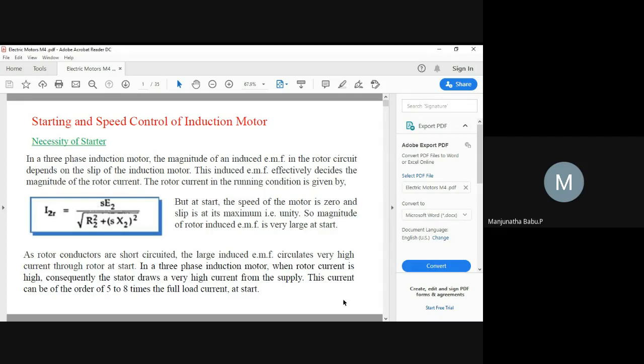At the starting, a small load you will be applying. Then you would have seen the value of the power factor. It would have been around 0.2 or 0.3, or between 0.2 and 0.4. With respect to that, since the denominator has a lower value, the current flowing in the line will be more. So to limit that current, we have to go for the starters.